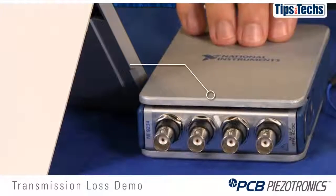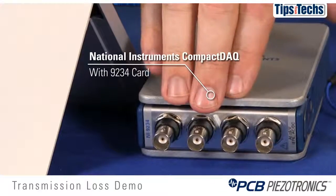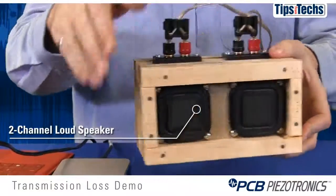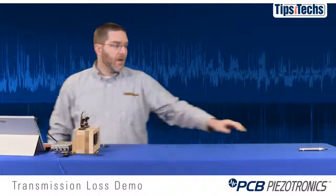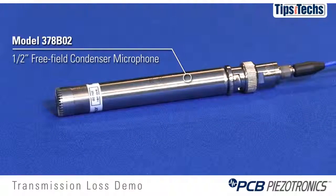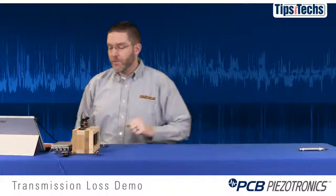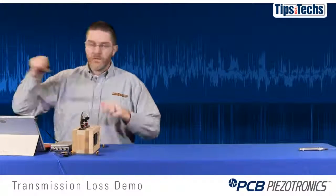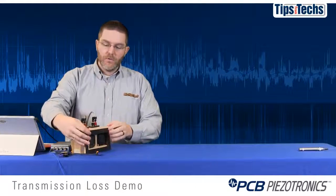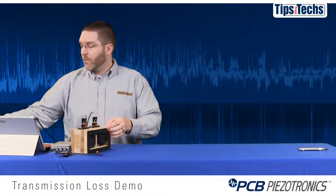We'll be using a National Instruments CompactDAQ 9234 card for our data acquisition system, a small 2-channel speaker box for a source, and a PCB model 378B02 half-inch free-field condenser microphone as our receiver. We'll take a gasket material and put that on our speaker to avoid acoustic leaks, and then we'll put different panel materials in front of the speaker and measure the insertion loss.